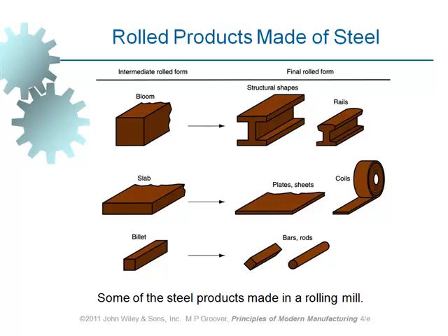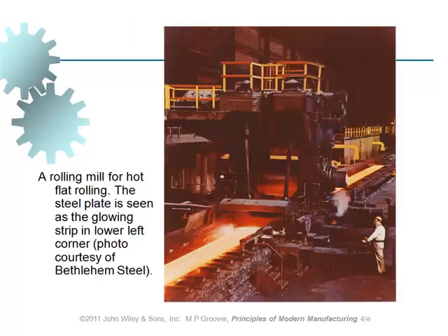However, in cold working, there is some residual stress left in the material after it is subjected to cold working. If we want to get rid of it, we can subject the material to an annealing process, which is leaving it in the furnace for some time at elevated temperature in order to get rid of the residual stress, which is possible. It does not often happen, but in case it is very important for us to produce a material which hasn't got any residual stress in it and is stress-free, then we can make use of this process.